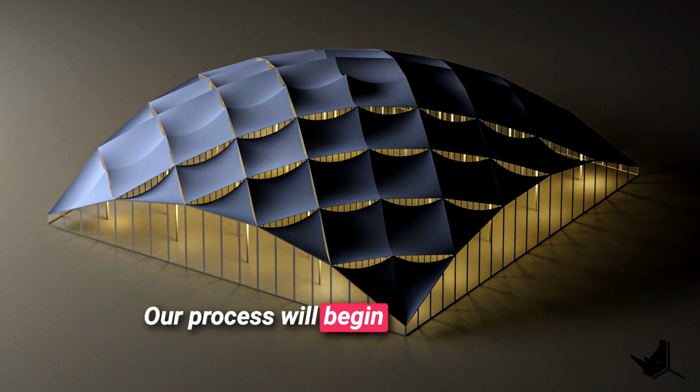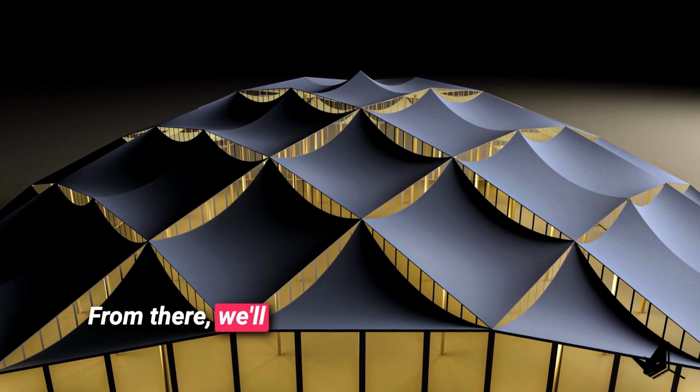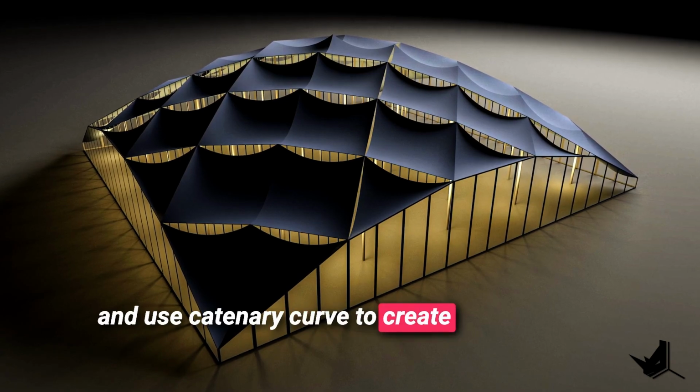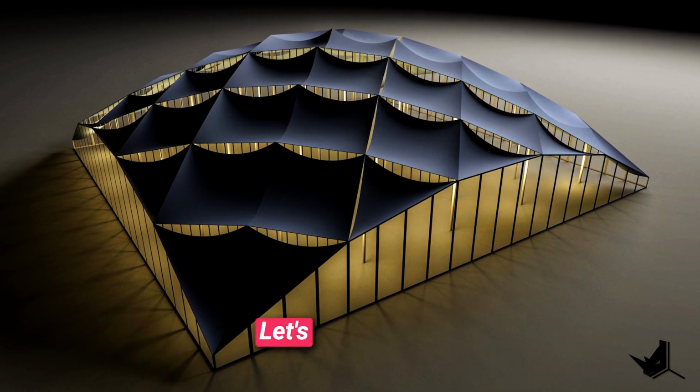Our process will begin in Rhino, where we'll generate a 2D diamond grid. From there, we'll move on to Grasshopper, where we'll transform the shape into mesh, lift it up, and use Catenary Curve to create roof surfaces with gaps that will form vertical glass panels. Let's get started.